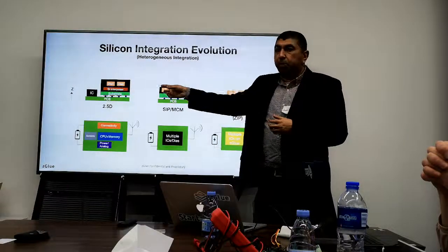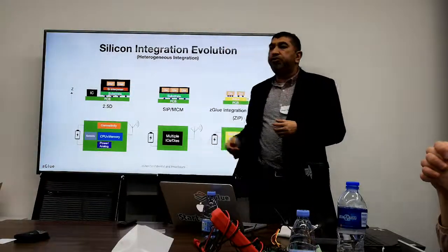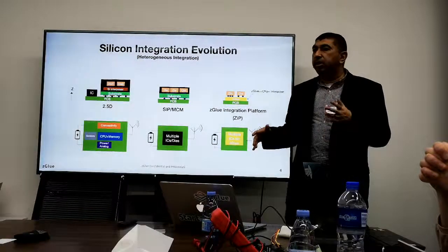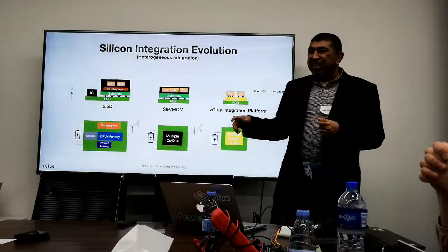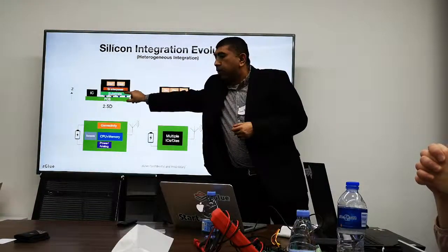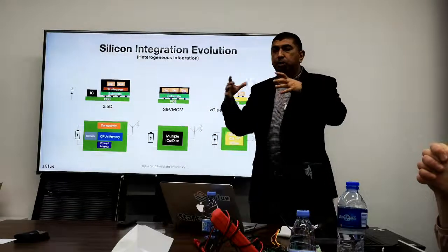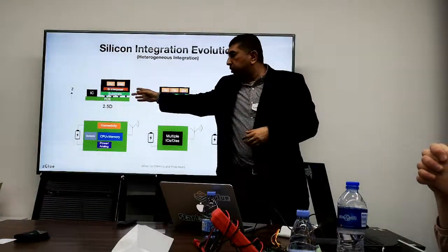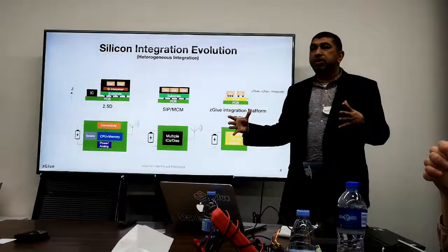The silicon interposer only provides a lot of wires going from die 1 to die 2, maybe a few thousand wires. And then this combination is put onto a substrate, and you see the package. That's the microprocessor going in servers. That then goes on the server PCB.